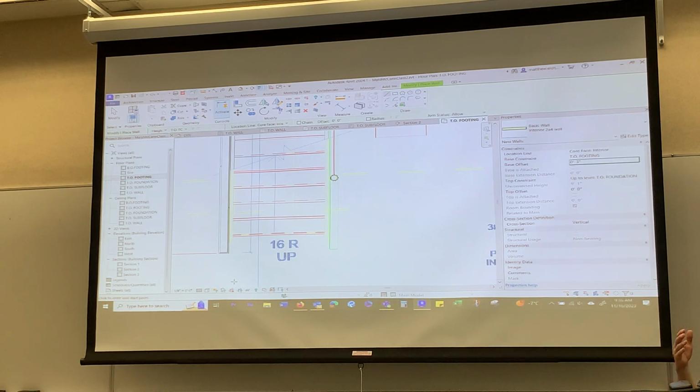Just so you know, okay, the elephant in the room. With pre-manufactured stairs, most builders in this style of house have a stair company build them off-site at the plant. The stairs are going to be at a minimum, and for this opening, 1 inch less than the framing. But they go in before drywall.